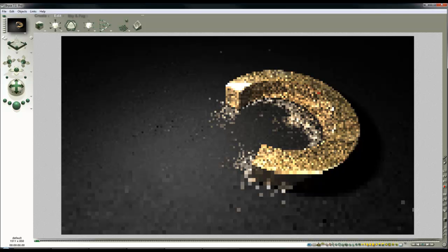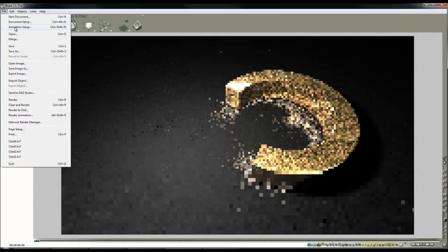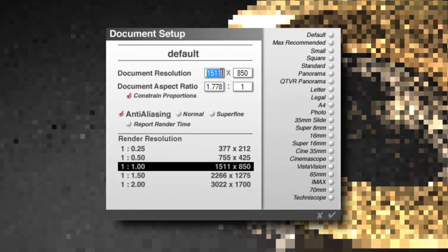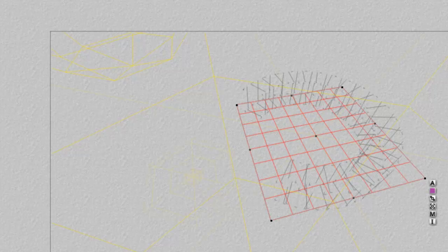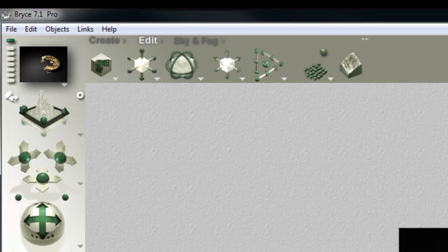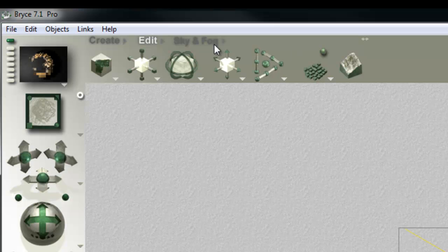And so to improve our previewing of this scene, rather than lower the rays per pixel, which will create a lot of noise, we still need the sampling, I'm going to use the document setup to reduce the size of the render. So now it's still looking a bit dark, and there's this very dark shadow region here. I could probably do with another light source. So at this point, I'll consider adding yet another light source that provides general ambient light.